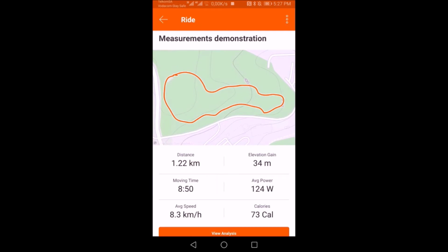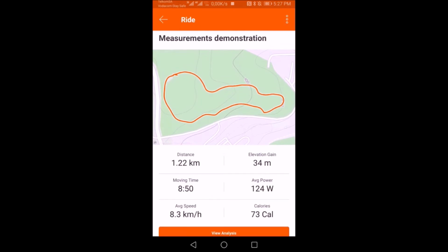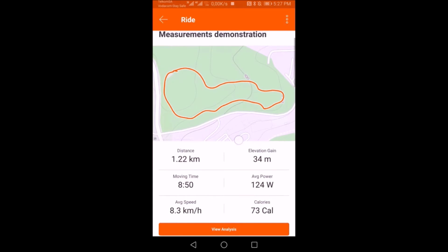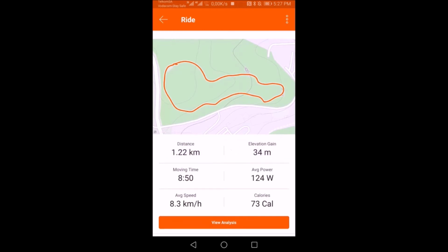And again, it is because there's the satellite view, or at least what the receiver is able to see of the satellites is always a problem, and that needs to be taken into account. When I start off the recording, it tells me that the GPS has got an accuracy of 23 meters. So there could be some error in terms of that as well. Then if you would, for example, also have a situation where there will be trees, there will be leaves, there will be water in the leaves, and these obviously also absorb signals, especially those that the satellites are transmitting at, and this will also give us errors.